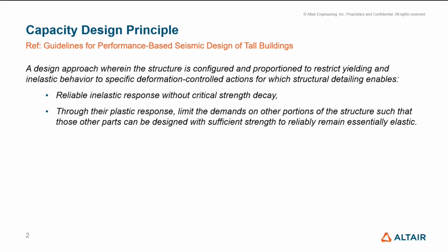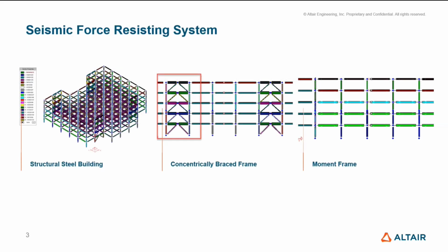So with this approach, the designer establishes which elements will yield and need to be ductile, and those which will not yield and will be designed with sufficient strength based on the forces imposed by yielding elements.